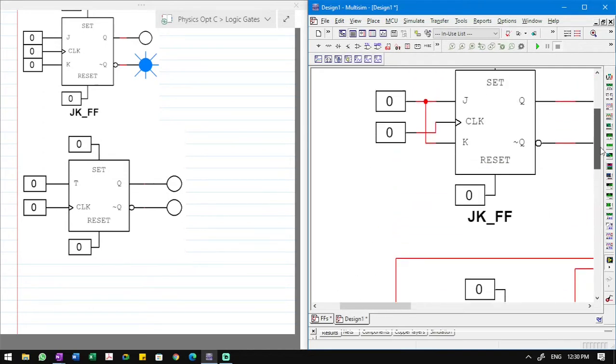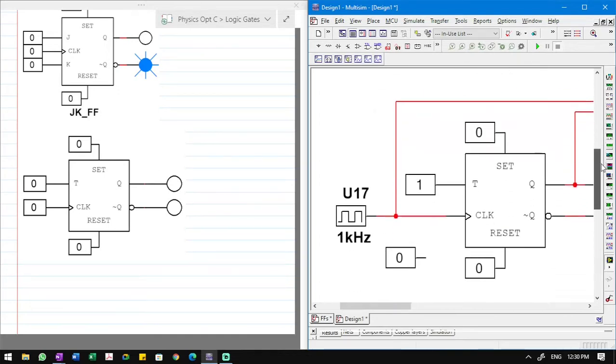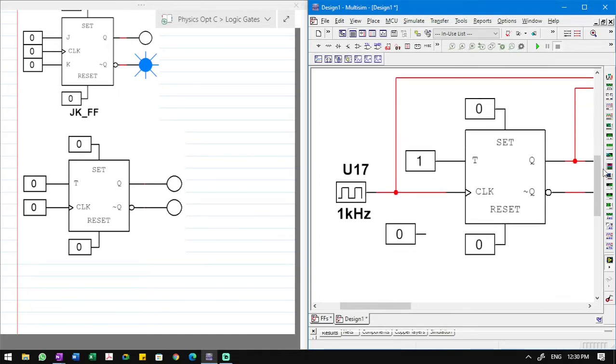Even before I go into that, apologies. The JK flip-flop has the inputs J and K tied to one control, and when you do that, you create what is called the T flip-flop. So the T flip-flop is basically a JK flip-flop, which is essentially a very specially connected SR flip-flop, where it has one input that you can control, either turning it on or leaving it off.